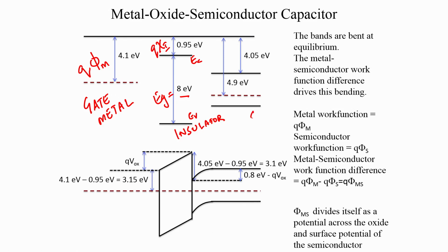And then finally, you have your semiconductor. Okay. So, we have not yet created the junction in this diagram. So, we have the semiconductor, and here you have some band gap. So, for example, let us say the band gap is, if you take silicon, about 1.12 electron volt. Okay. We have some band gap, and the semiconductor is doped p type, which means that the Fermi level of the semiconductor lies a little below mid gap.